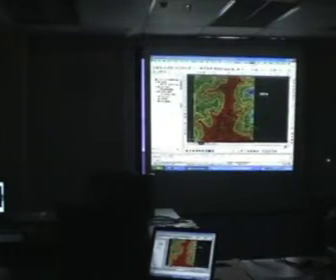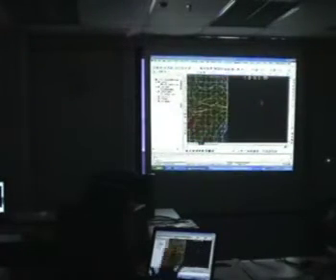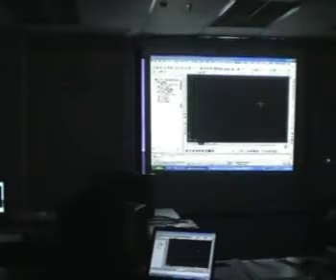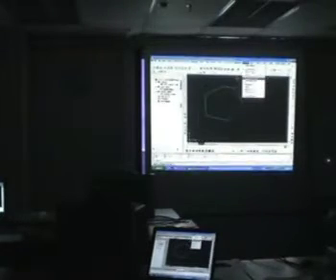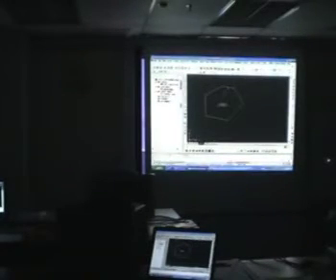Here we've got parcels and tables. I'm just going to zoom to a blank spot so that the triangles don't crowd what we're doing. I'm going to draw just a non-polyline here and say, okay, let's say for example we want to use this as a parcel. I'm just going to define from polyline and just pick the line. You can see how the parcel number with the area appears automatically.